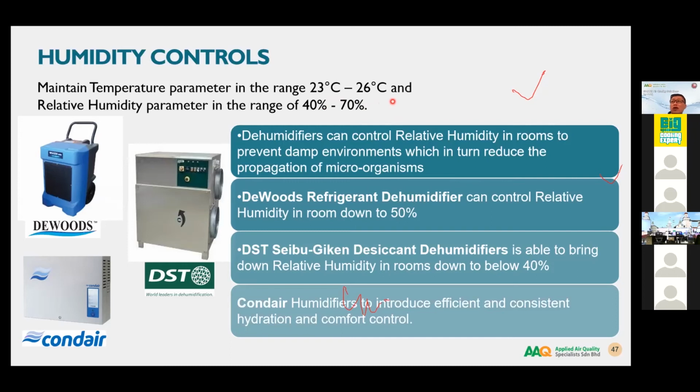Let's say you're working in an indoor environment and the building is an old building. The ACMV is, of course, the old ACMV and it's not designed to cater for 100%. Maybe when you follow the guideline, you cannot improve further, or you do not want to improve further on your ACMV. Maybe you can reduce the amount of people working inside your building. Okay, that is another way to reduce risk, reduce the amount of people inside the working area or your room.